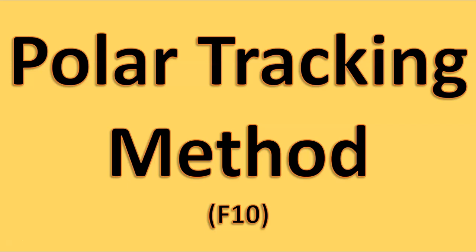Okay, so polar tracking. Very, very useful, especially if you got something that has angles, and they are very common angles that you can use. And what I mean by common angles is 45, 30s, 60s, angles of that nature that are typical that you're going to see a lot. So you could set up AutoCAD to say, okay, anytime I see those angles, use those, or I can use that to create or copy or modify something along those angles. Really, really useful stuff.